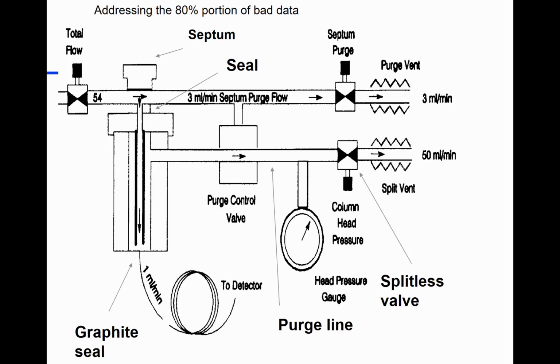Purge line plugging, valve sticking on the end. And so you always start that way. You start looking for leaks. Where are they? Typically, they're one of those rubber seals. They're seldom on this end. Normally, they're up there or up here. Sometimes here.